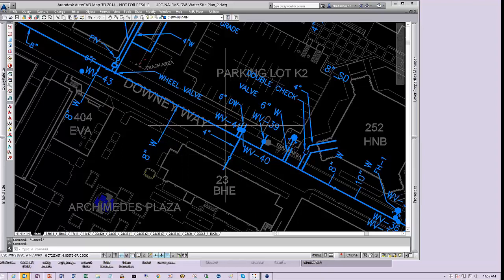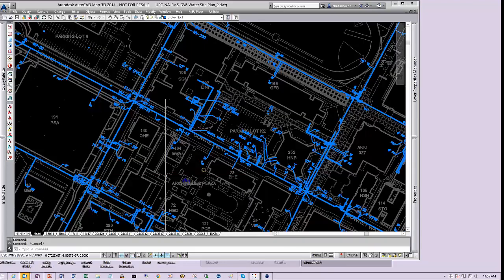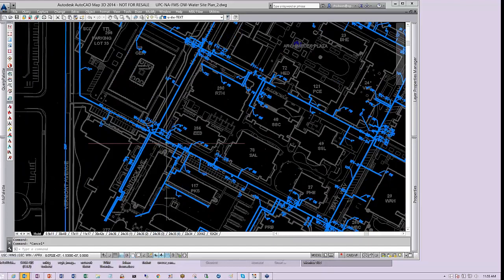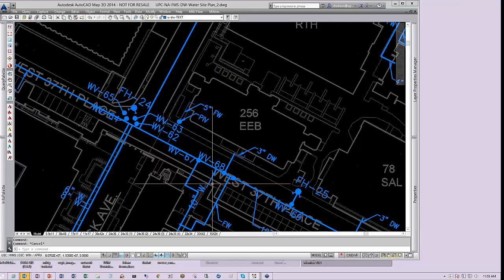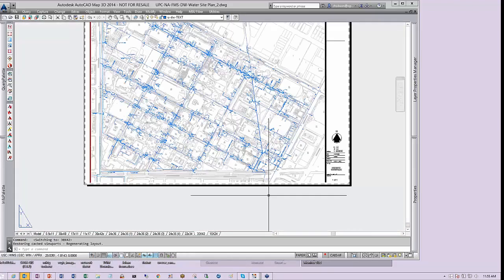And also what happens is people don't change things between one layer and another. So you can go in and see that something may be on a different layer than what the text next to it says it is. And so those are all challenges. In terms of CAD, the other thing is the coordinates for this would be just laid out to fit on the piece of paper. And north, in this case, is north, but it could be rotated to match a building layout.